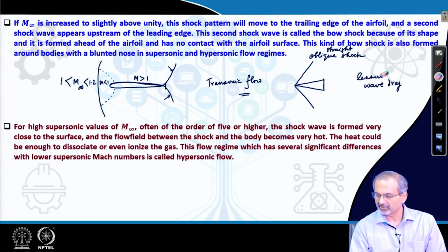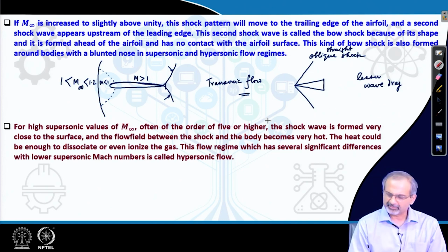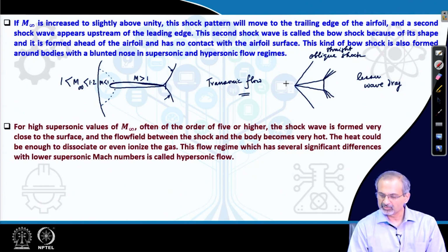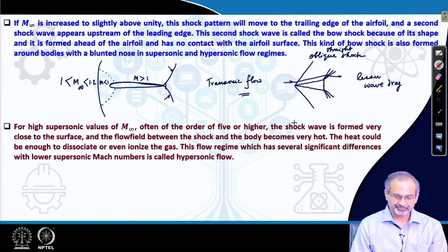So, these kinds of sharper shapes are more preferred at supersonic speeds with a lesser drag penalty, and you now know how to draw the flow field. So, there will be an expansion here further, because the flow is turning away. So, how would the streamlines come in? They will come in like this, they will turn slightly through the expansion and become like this. I am not drawing it at the lower part, you can do it yourself later on.